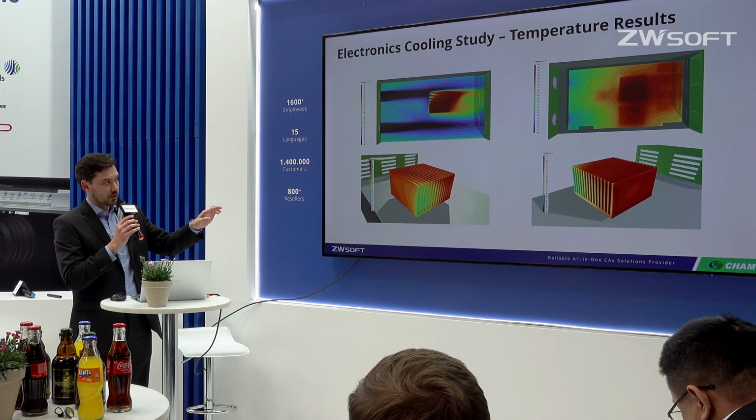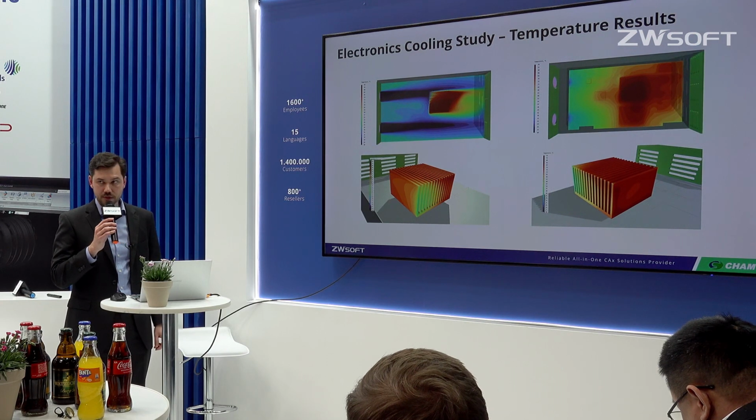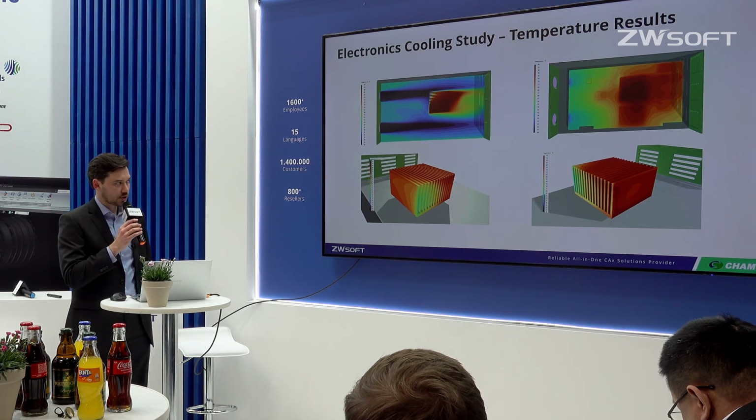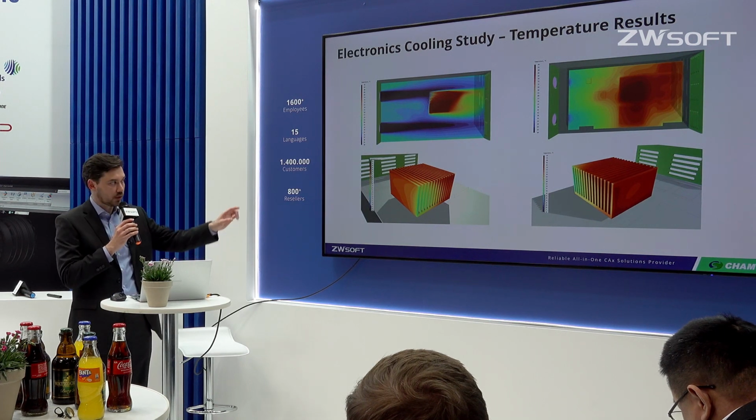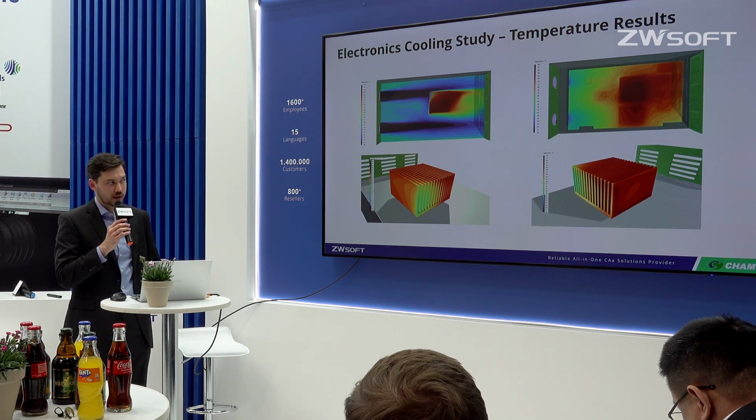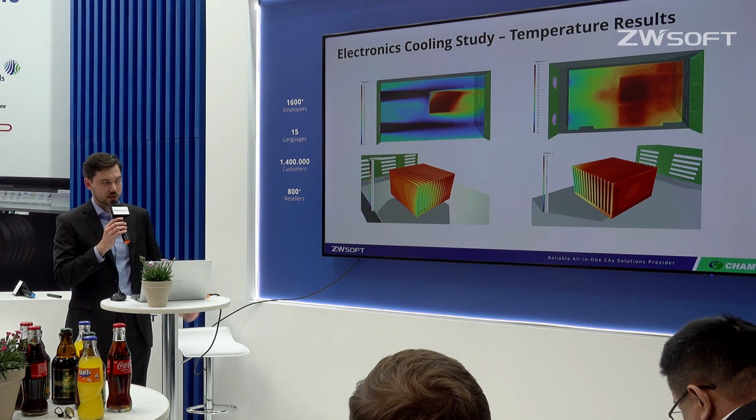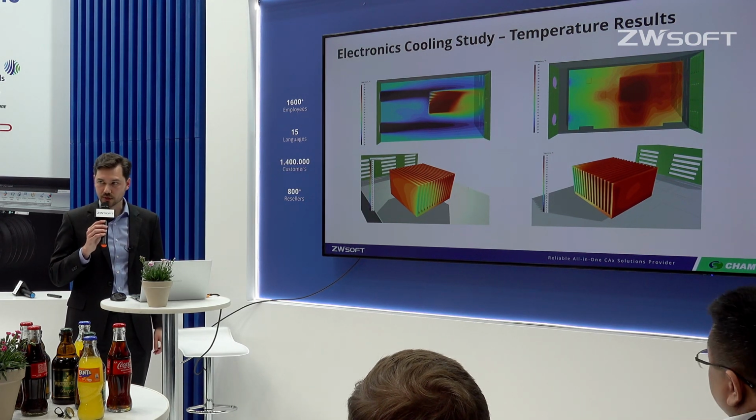The lower two images show two perspective views of the heatsink. I've just kept them in here to illustrate that one half of the heatsink does seem to be working quite well, signified by blue regions, and the other half in the right image is almost all deep red, signifying no heat transfer. Let's take a look at the findings and what these findings might suggest we do to remedy the problem.